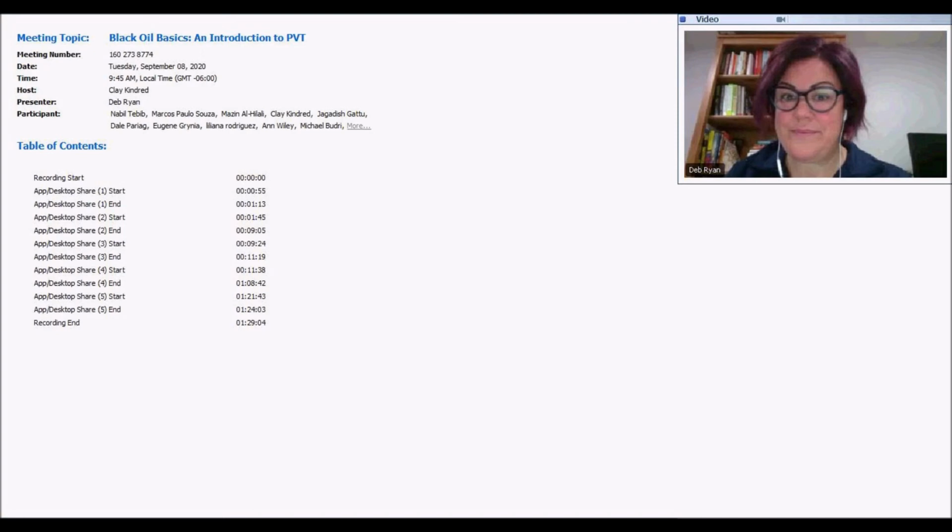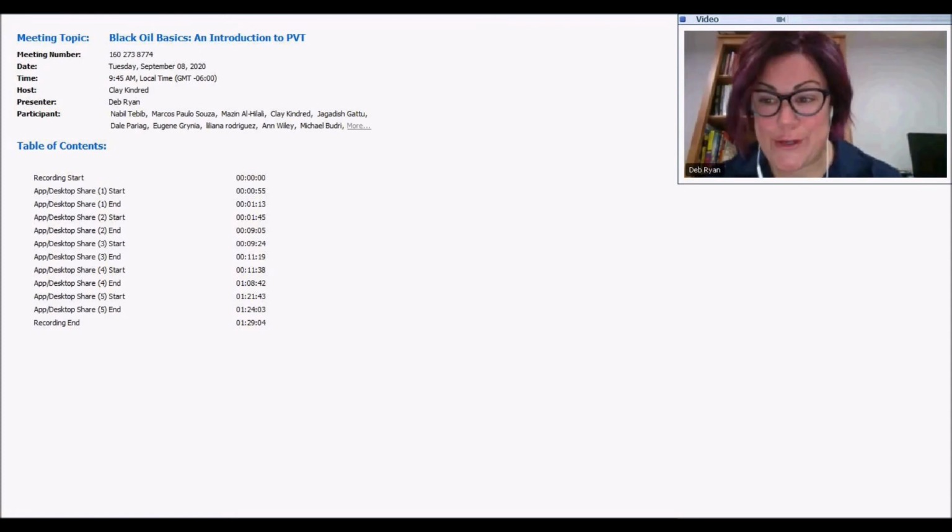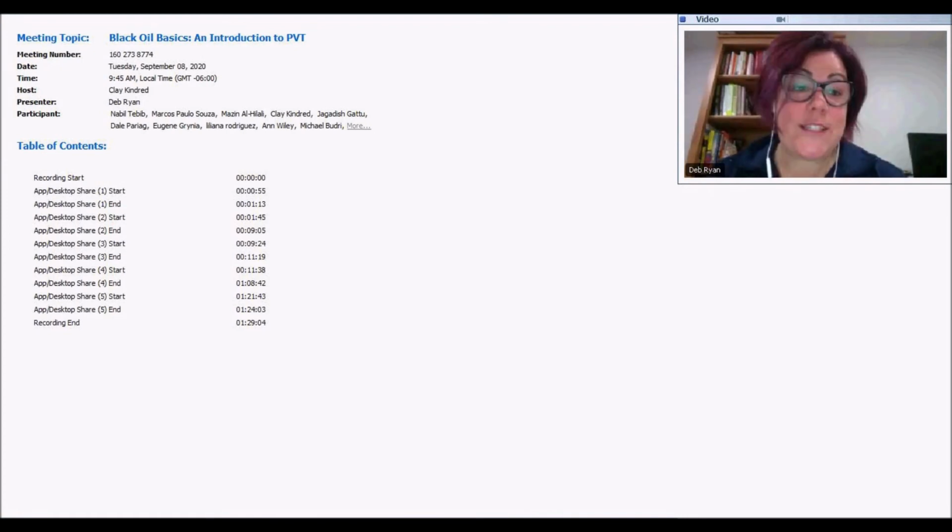One of the questions that came in, I believe you addressed, says: in the absence of PVT lab testing, is there a rule of thumb to calculate the initial gas-oil ratio? So you really need to use your production data. If you don't have production data because you're early in appraisal, and I'm actually working on one like that at the moment, it's going to be through analog, unfortunately.